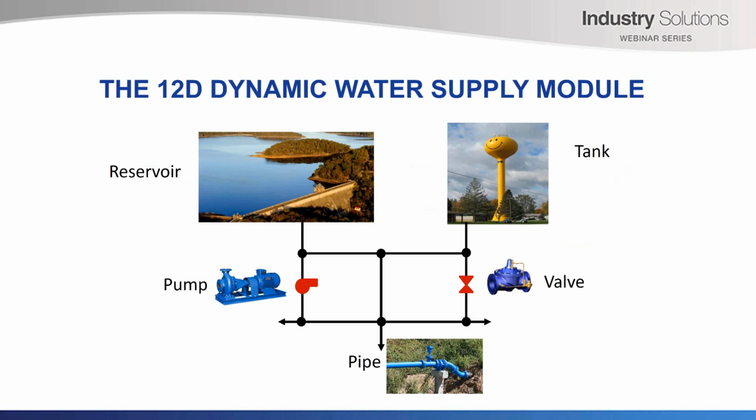So, like all the software in the Three Waters trilogy, it's a linked node model. There's probably no practical limit to the size of the networks. It's very fast. Most of the runs I've ever looked at have been less than a second, maybe up to a second. So you can model every deflection, house connection, reducer, valve, every component in your network without detriment. You can easily have 100mm long pipes in this. So, all of these deflections that you'll see in the system you can model.